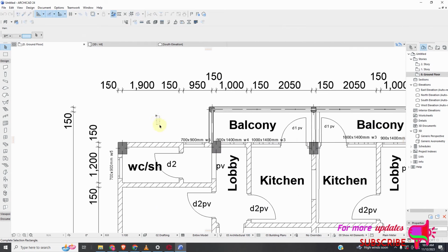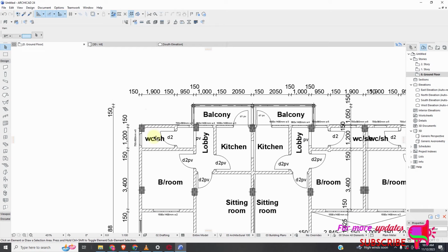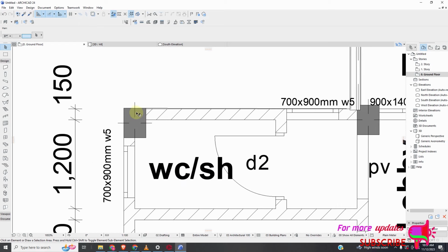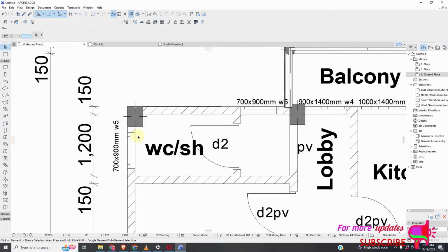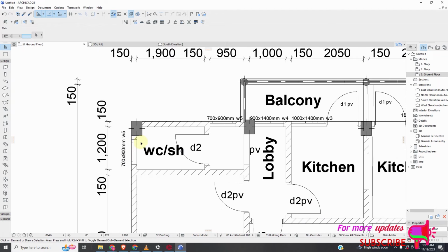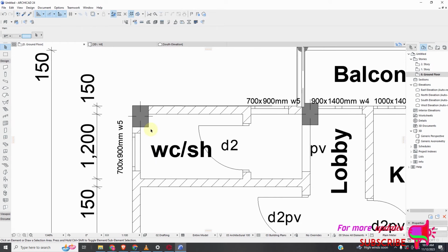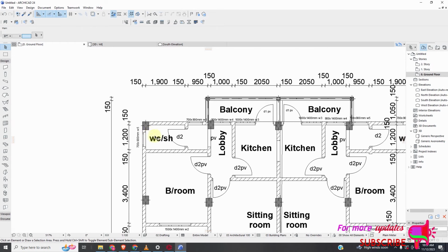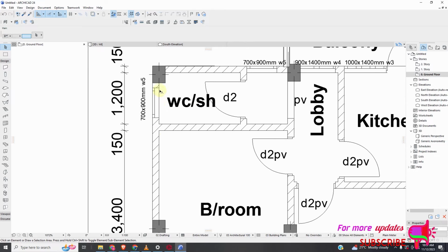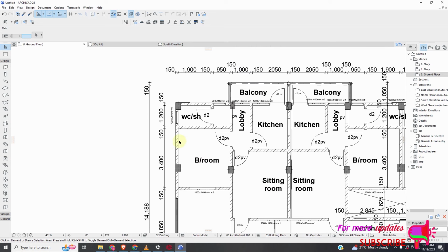Okay, so we're going to use the grid for this wall and the grid for this wall to scale. Remember, grid is usually at the midpoint of a wall. So not columns, because you can see if you put your grid line here, it is not at the midpoint of this wall. So grids are always at the midpoint of a wall. So that's the point that you should note very seriously. So first I should draw a grid at this wall and a grid at this wall. So you use it to scale.